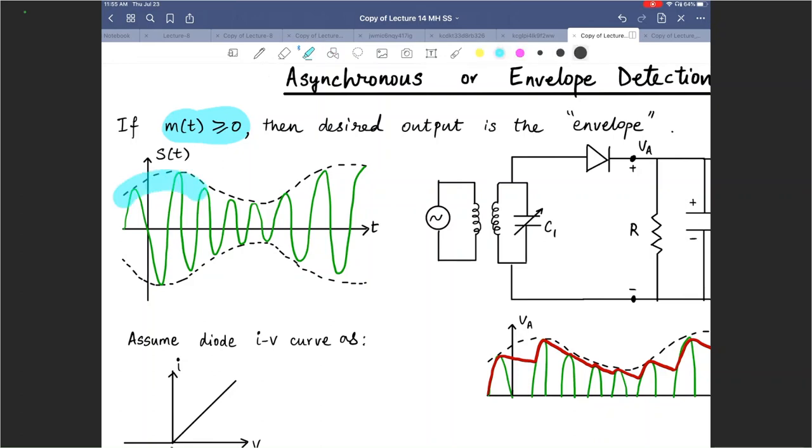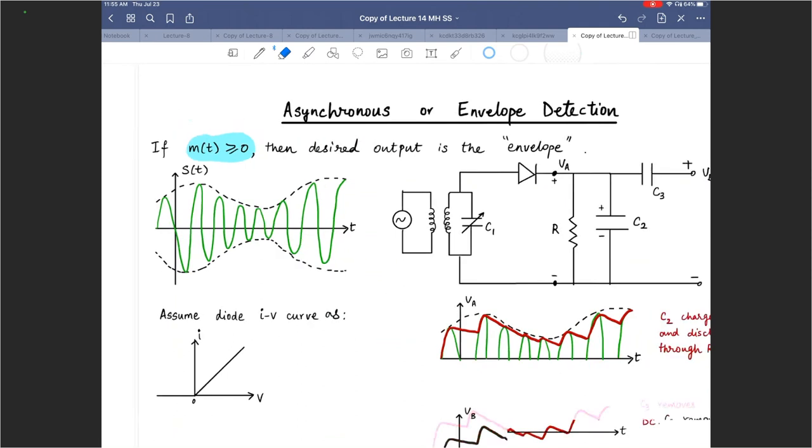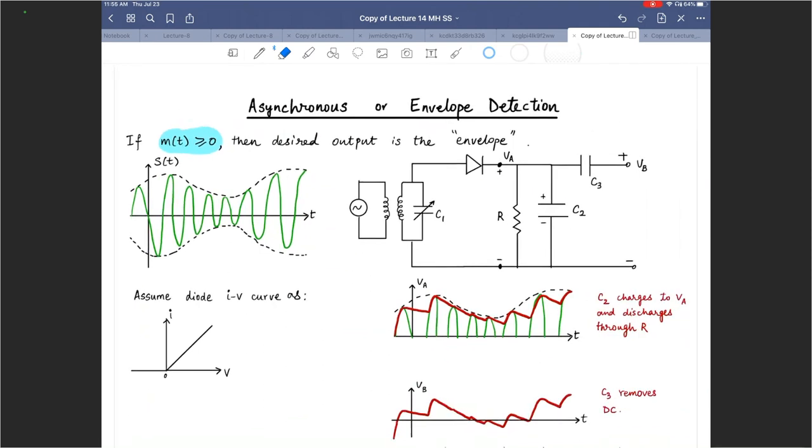It will go below 0 like that, and there will be a phase reversal of the carrier, which will be reflected in a negative sign, or the opposite sign, in the output VO of t in comparison with M of t. You don't want that to happen, which is why you want to keep M of t greater than or equal to 0. So we can fix that by adding a bias to the signal. More about that later.